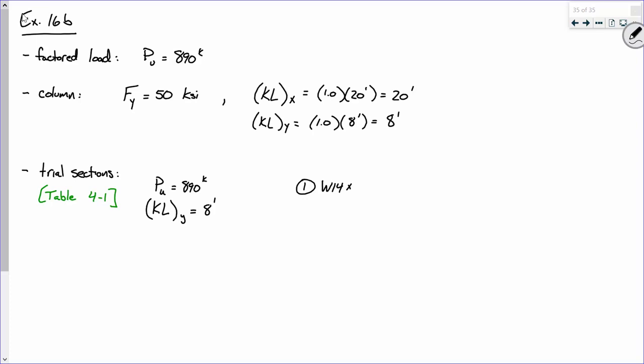Okay, the 82. You're saying the W14 by 82. Does anybody second that choice? Okay, all right. So you're saying the W14 by 82. Now, just so everybody's clear, you picked that because it has a PPN of what? 960? 968.